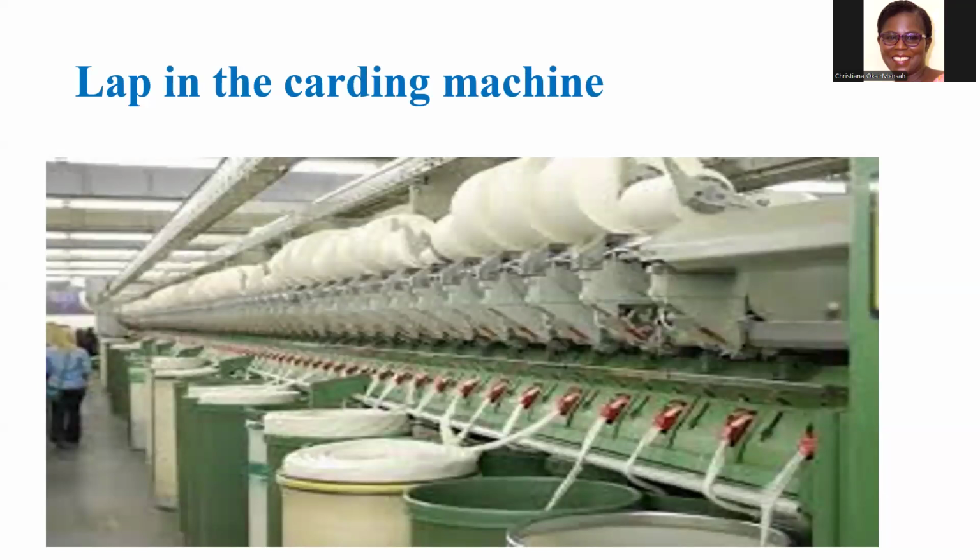So this is the carding machine. What you have up there is the lap, which has been rolled like a tea roll. It has been packed. The carding machine inside here will open the cotton again, then take away extra impurities, and then it will come out as a sliver with a little twist. The slivers are packed into these barrels for the next process. So that's the carding machine.